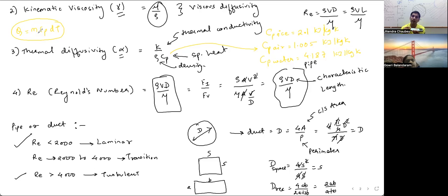For that body, how much heat it has lost, you'll have to use the formula MCP dT. And whatever heat the body has lost must have been conducted and convected, because if the body is losing heat, it will be either in the form of conduction or convection. So that heat lost can be equated to the heat transfer.